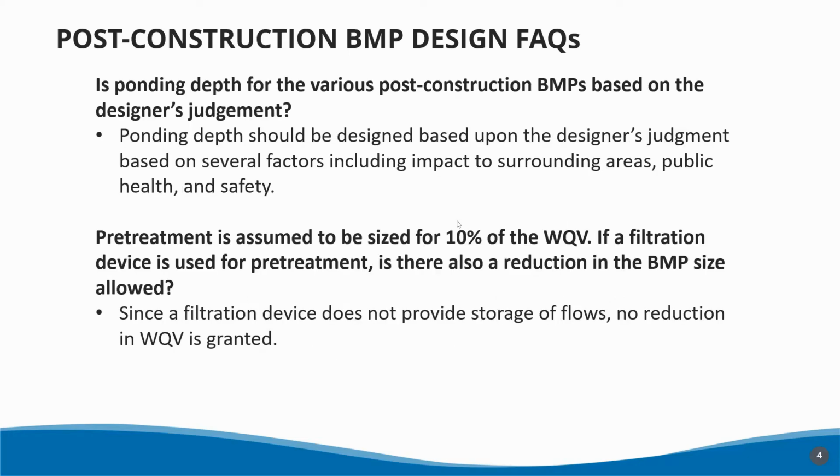Is ponding depth for the various post-construction BMPs based on the designer's judgment? So yes, it is. The examples that we currently have in the manual assume a ponding depth of 6 inches, but the designer needs to be aware of the type of facility being designed, as well as its location.